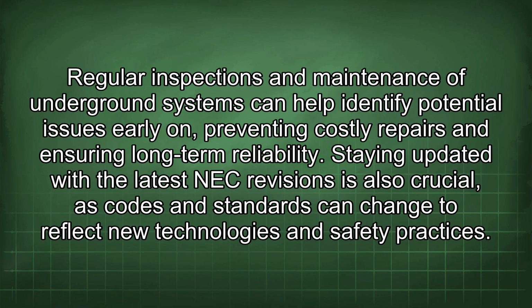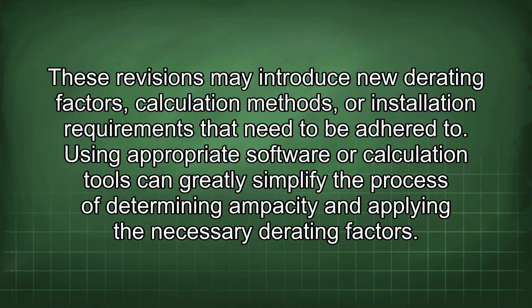reliability. Staying updated with the latest NEC revisions is also crucial, as codes and standards can change to reflect new technologies and safety practices. These revisions may introduce new derating factors, calculation methods, or installation requirements that need to be adhered to.